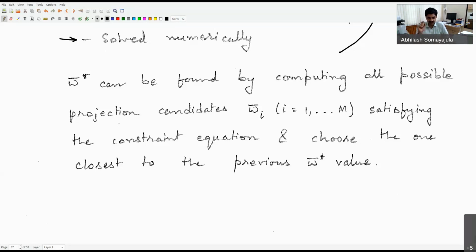Particularly, if you remember, we looked at the idea of integral line of sight control, and we saw that when we include the integral term inside the tan inverse, finding that gain can be quite a challenging task. Therefore, we went ahead with a revised integral line of sight scheme, which was nonlinear in nature, but at least it gave us some stability properties.